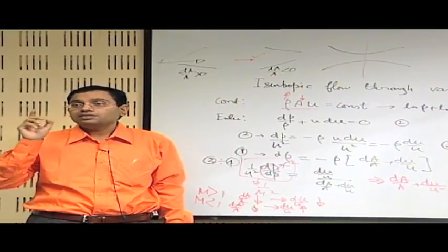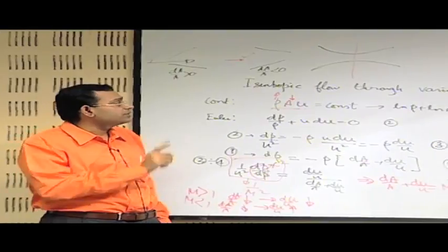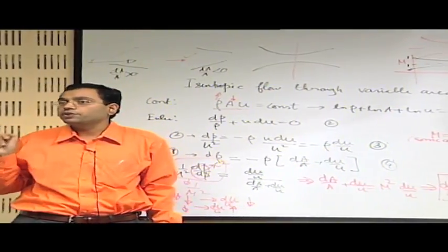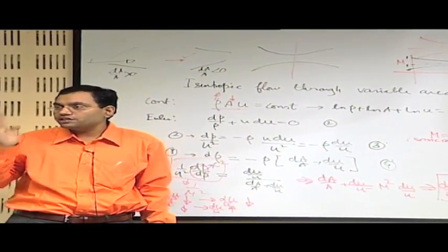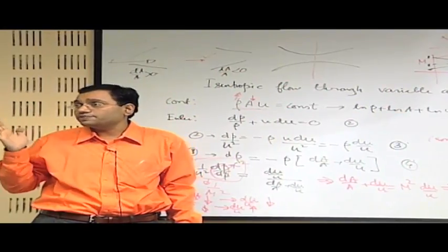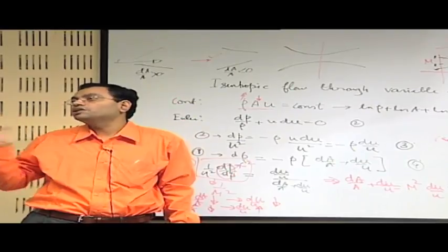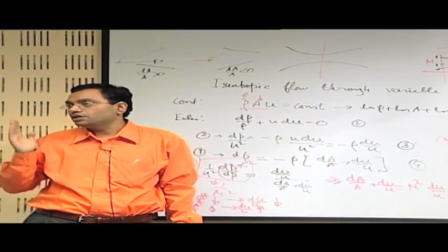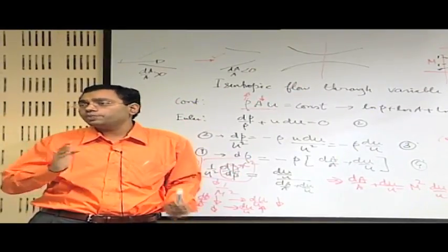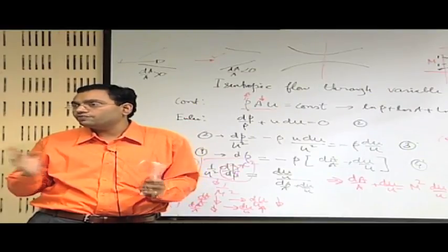Again remember, there are very important assumptions associated with it. The assumption is it is an isentropic flow. So if it is a flow with friction and flow with heat transfer, then the location of this sonic point, Mach number equal to 1, shifts. It is no more at the throat, it is at either the upstream or the downstream depending on the heat transfer in the flow and friction in the flow.